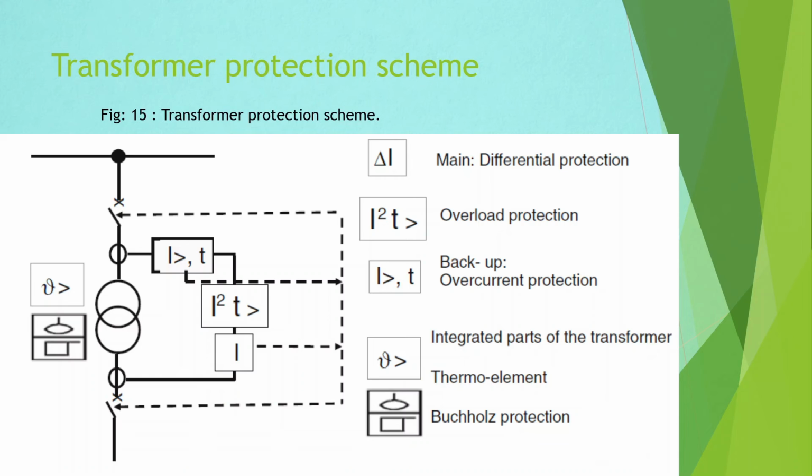The bay IEDs continuously submit the measured instantaneous currents and the position of the isolators to the central unit. The central unit detects the busbar segments and the appearance of the fault. If fault detection is definitely recognized, all feeders connected to the faulty segment are tripped without any time delay. The backup protection of the busbar is performed by the protection system of the feeder connected to the faulty busbar